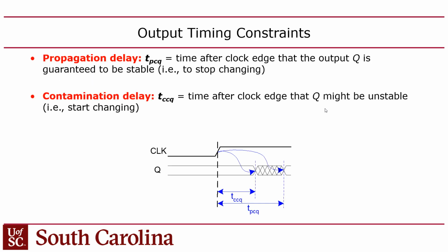Okay. Now the problem is flip-flops have another property that you can't change, which is called the setup and hold time. The setup time is how long the input into the D input has to be stable prior to the clock edge. Now, when do you know the clock edge happens? Well, the clock edge happens when the clock passes the halfway point between power and ground, right? So whatever half the supply voltage is, whenever the clock passes half the supply voltage, that's considered to be the time of the clock edge.